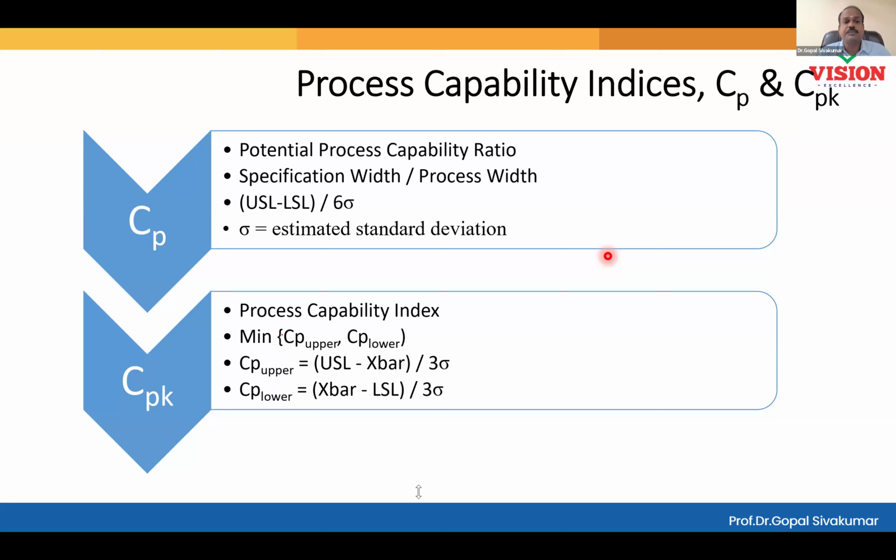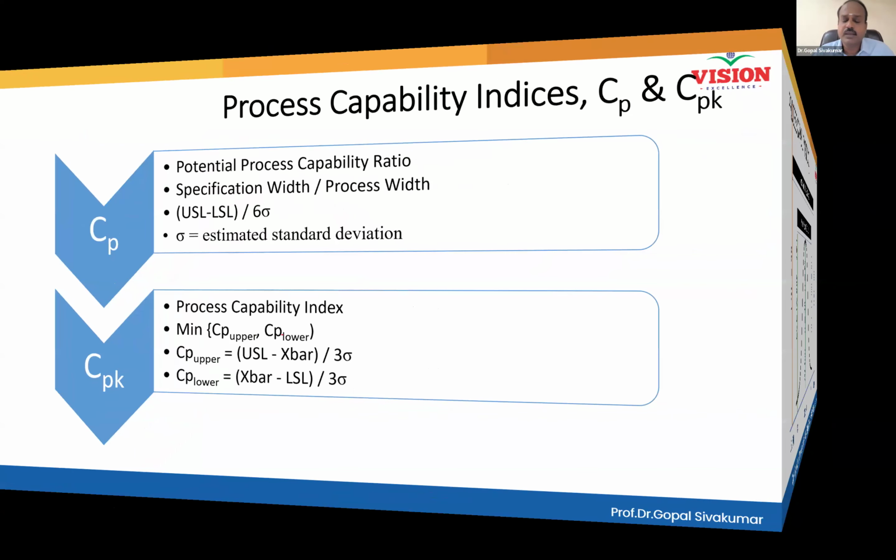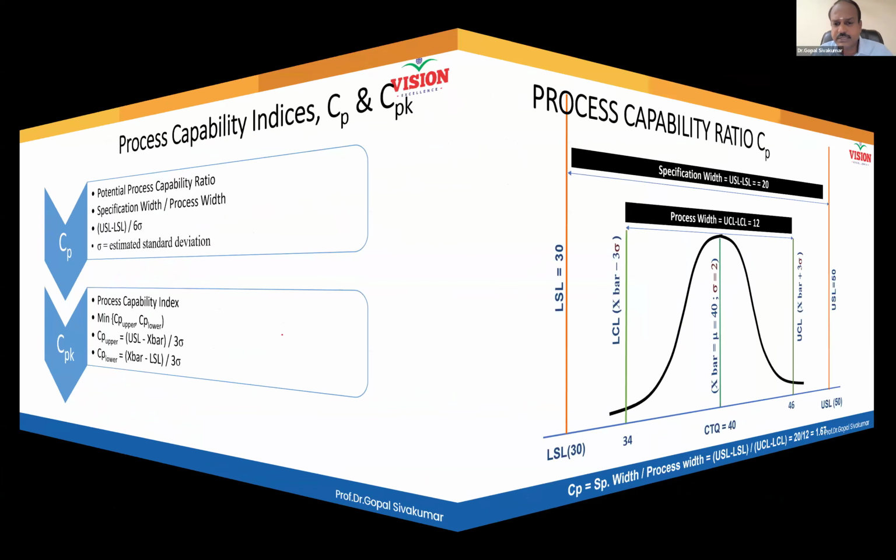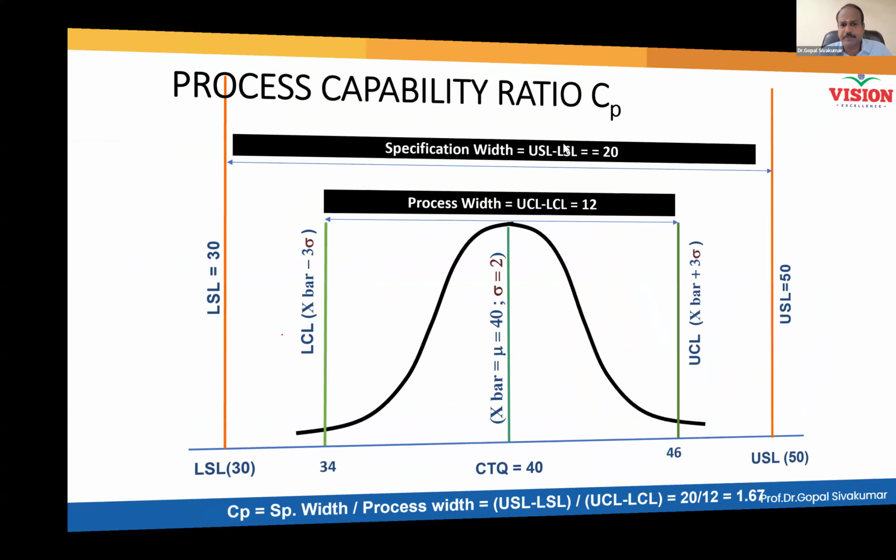If that is understood, you can calculate both Cpk and Ppk. Otherwise, the formula, everything remains same. See here formula. These are all same, but the sigma should be within standard deviation. Hereafter, you should say within standard deviation. So these things we already discussed during the Cpk discussion.